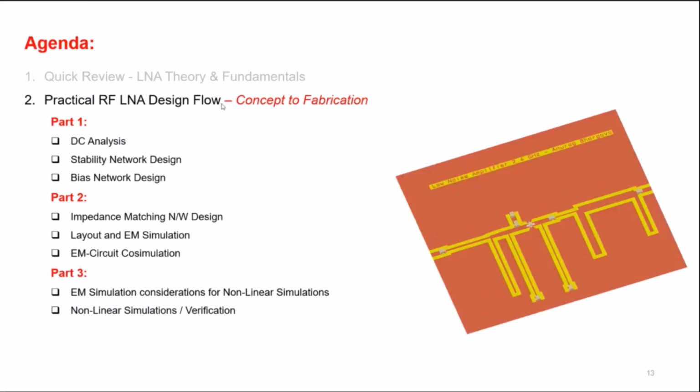So now we can start with this fundamental, just to summarize. You decide your fabrication technology. For now, I'm assuming most of you may want to do board design, because this is simplest to do. You can go ahead and fabricate, you can test, you can refine your design process so that what you simulate is exactly what you measure when you measure your circuit using a vector network analyzer. That should be the goal. And anything which is not going right in between, you can refine and you can achieve that.